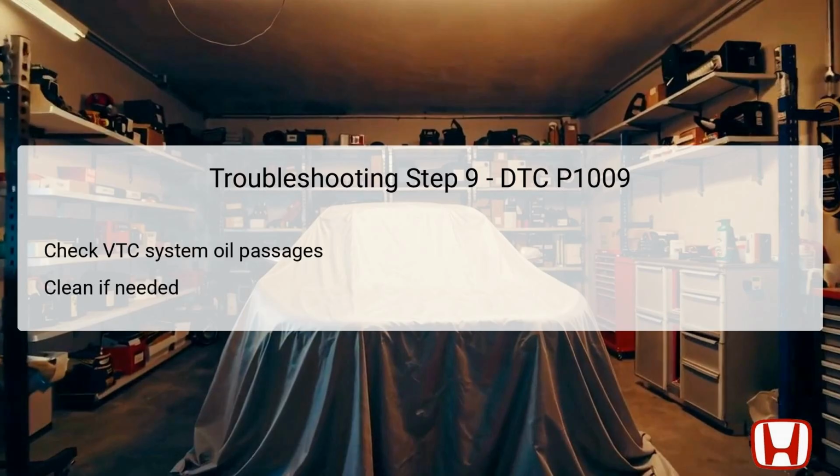Any blockages or restrictions within these passages can lead to faulty operation of the VTC system, which would directly contribute to code P1009. Cleaning the oil passages is essential if any contaminants or debris are found, ensuring that the oil flow is optimal for the actuator's operation. This cleaning should be done carefully to avoid introducing additional debris into the system.